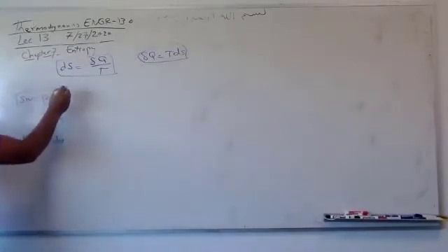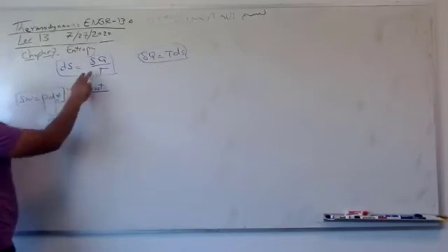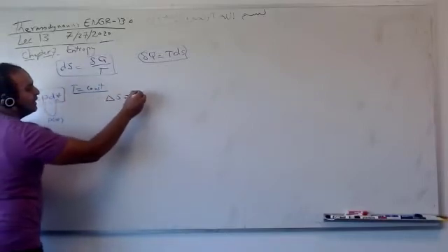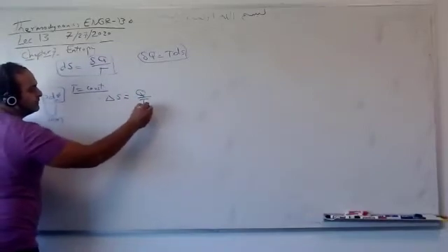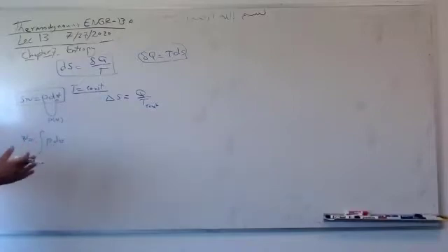For example, if T equals constant, we can integrate. So delta S, for example, dS equals Q over T0, where T is constant. When does this happen? For reservoirs, for example, ambient, ocean, so the temperature remains constant.